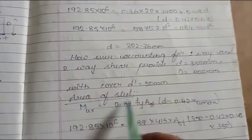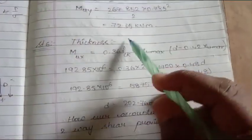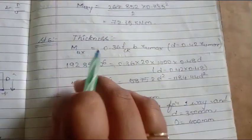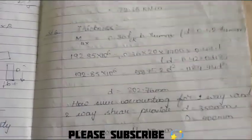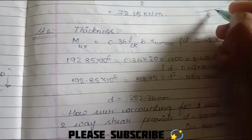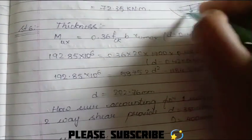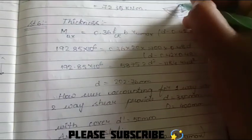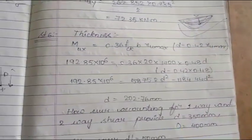Next, we are calculating the area of steel. Remember, first we will be taking the MUX and MUY. In this, see, MUX we got 192, and MUY we got 72. So the greater moment, we will be considering this. Whenever we are calculating any thickness or these values, you will be taking the maximum one, the greater moment, because if we are designing it for the greater moment, it can take any value in between that. But whenever we are taking the lesser one, if it is subjected to the greater moment, it will fail.